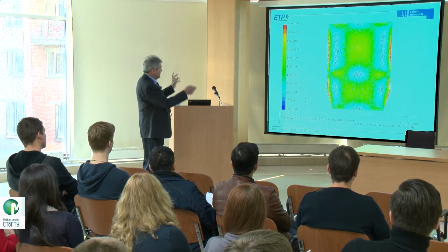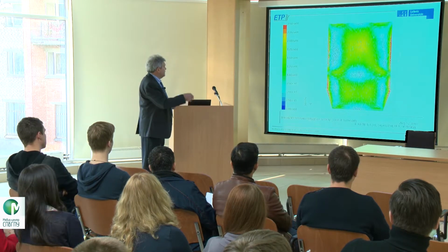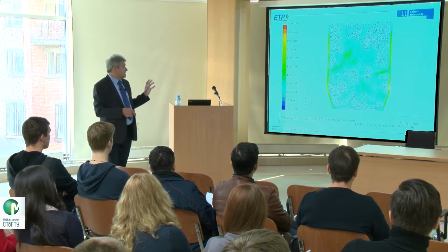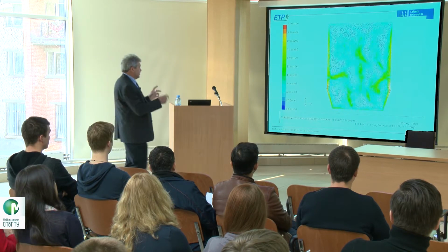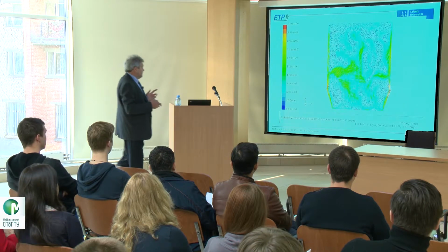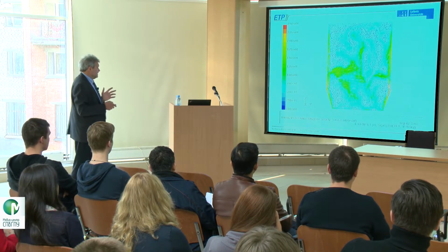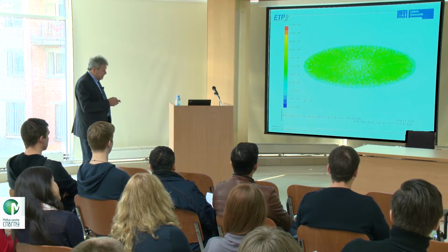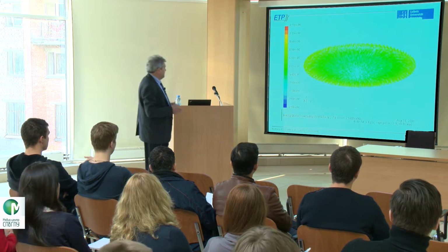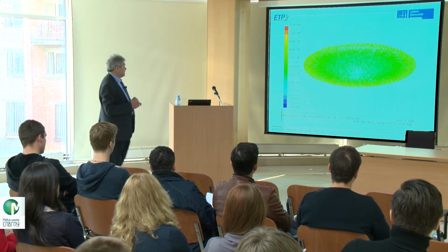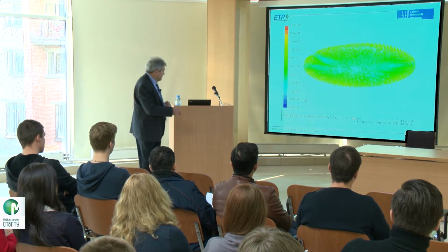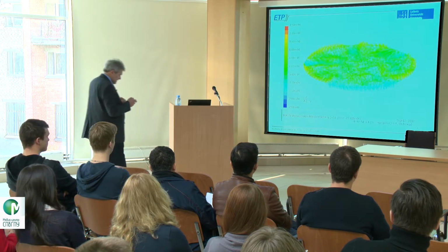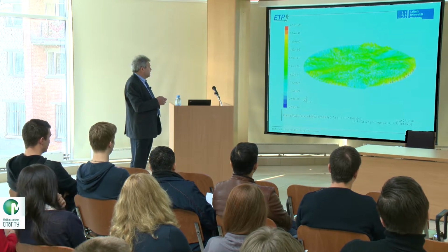It starts very homogeneous. You have typical flows which are going here in that direction. But after a certain time, around 10 seconds, it becomes more or less chaotic. And this chaotic flow, you can imagine, very strongly mixes the melt, and therefore you have a very homogeneous melt distribution. The next simulation shows the middle line, and also in the beginning this is quite quiet, but after again 10 seconds, here you can see the time is running. After around 12 seconds, it starts to move up and down, and this is also the reason for the strong mixing.